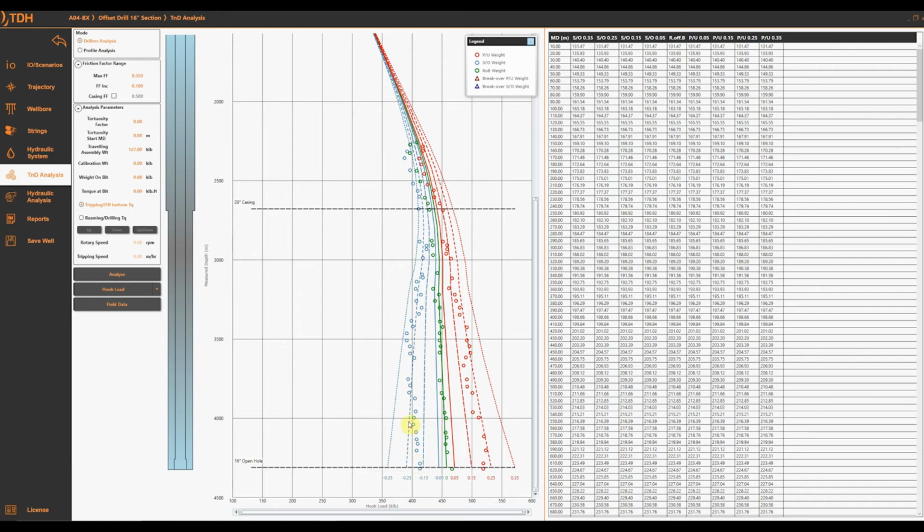We could go back and see what changed around these depths, where the trend changes from increasing to decreasing and vice versa, and maybe do a little bit of an interpretation of what was going on hole cleaning wise and what kind of changes were introduced. But for me right now, I could say that for the majority of the section, I can expect 0.3 friction factor for slack off and up to 0.25 for pickup. If I want to be a little bit conservative, I would say 0.3 for both pickup and slack off.